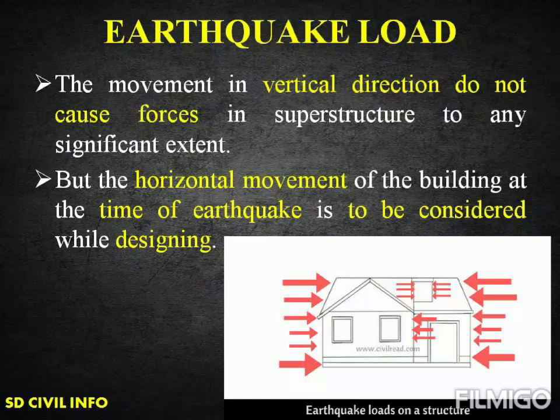Here, the movement in the vertical direction does not cause any forces in the superstructure to any significant extent, and so the vertical force doesn't affect much during an earthquake, but the two horizontal forces cause movement of the building at the time of earthquake, and hence these two horizontal direction forces are considered in the design.